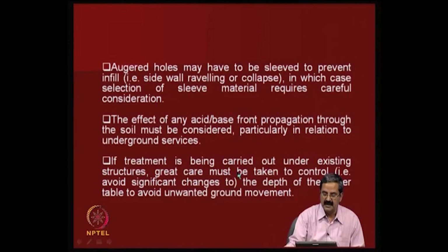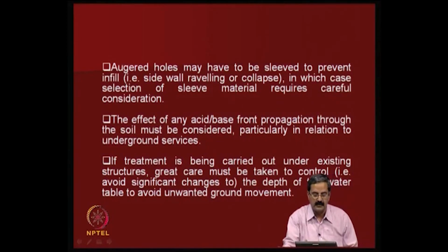If the treatment is being carried out on existing structures, great care must be taken to control the depth of the water table to avoid unwanted ground movement. Actually, that is another important point, as I just mentioned, that water table control is very important.